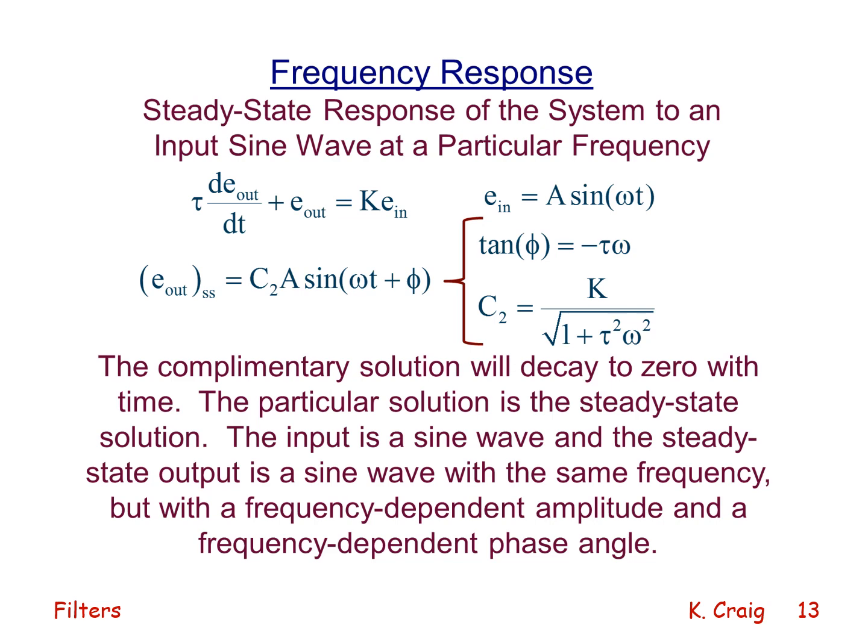Frequency response. Frequency response is defined as the steady state response of the system, any linear system, to an input sine wave at a particular frequency. Here we're talking about our first order system, our first order linear constant coefficient ordinary differential equation. If the input is a sine wave with an amplitude and a frequency, then the output at steady state, after all the transients have died away, will be a sine wave, same frequency, but the amplitude will be a function of frequency, and there will be a phase angle that's a function of frequency.